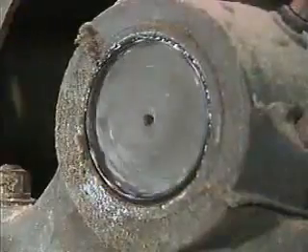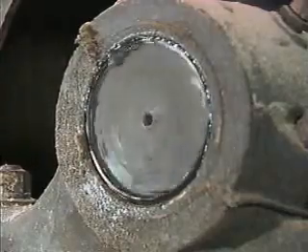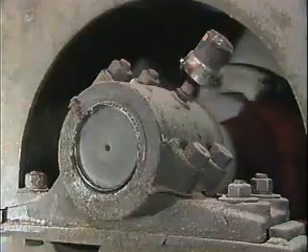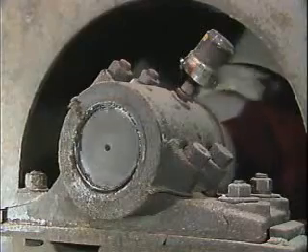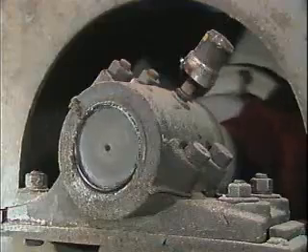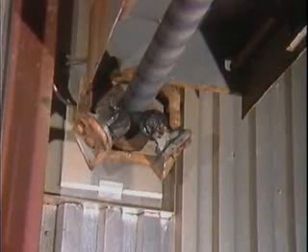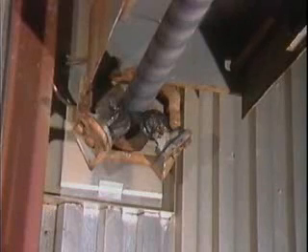Greases are also used to lubricate bearings in low-speed applications that don't generate much heat. Grease is frequently used when the running speed of a plain journal bearing doesn't exceed 200 to 300 revolutions per minute, or RPM. Finally, lubrication doesn't have to be done as often with grease as it does with oil. So grease is commonly used in situations where frequent oil lubrication is difficult to accomplish.